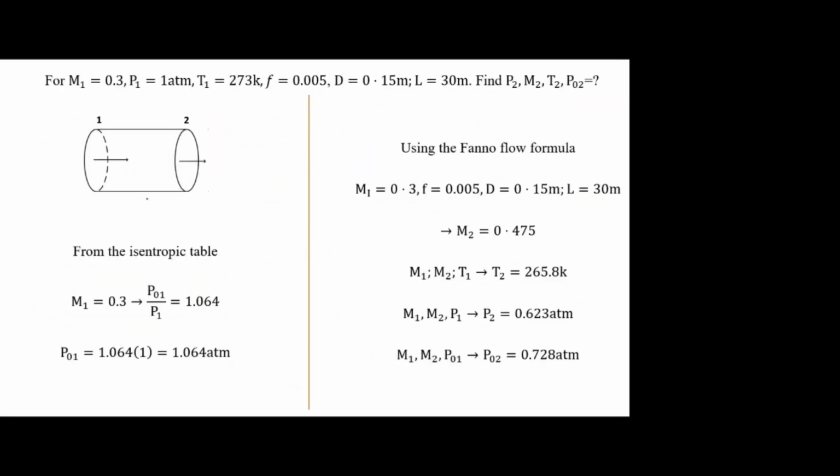Here also, we don't know how the inlet flow, whether subsonic or supersonic, will be affected due to the friction. So they are checking using two problems. First problem they are taking a subsonic Mach number, second problem they are taking a supersonic Mach number. But this flow phenomenon is almost similar to the Rayleigh flow. Here also, both subsonic and supersonic can maximum be accelerated or decelerated to 1. Okay, subsonic will be accelerated, supersonic will be decelerated.